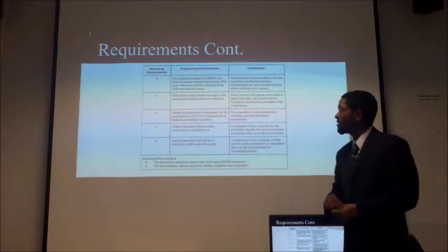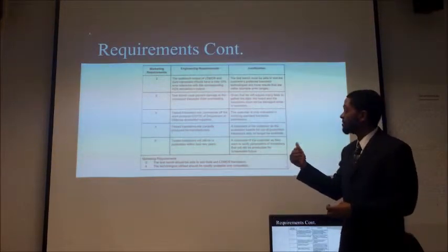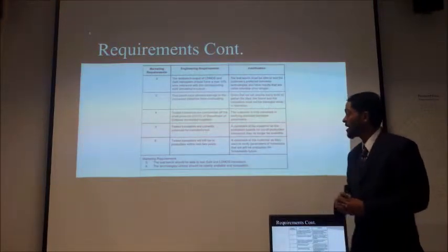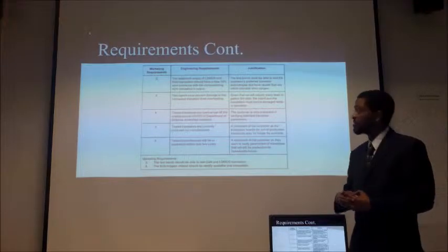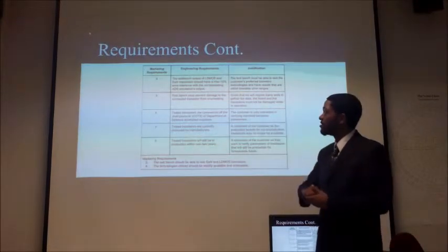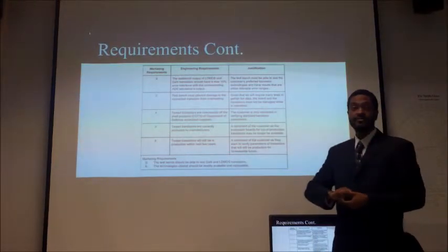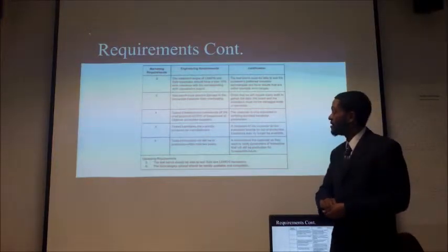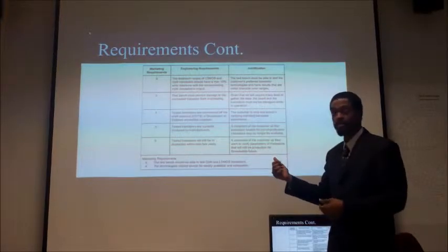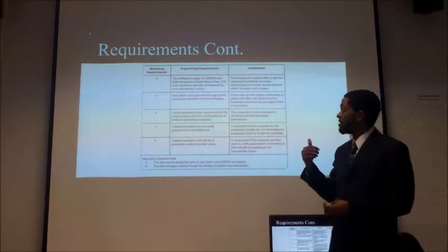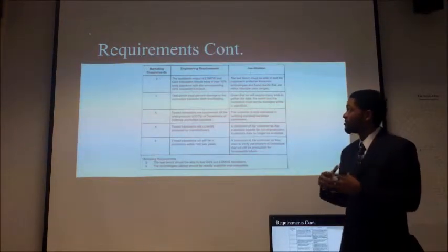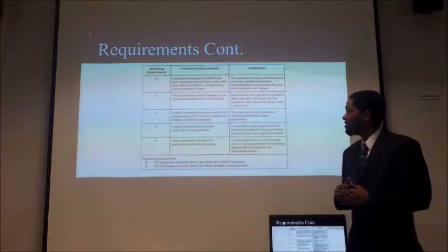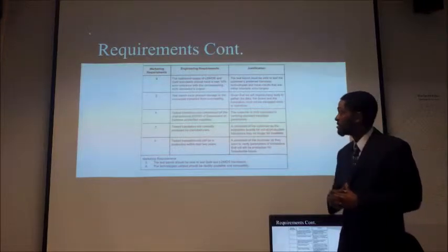Moving on, the next engineering requirements were derived from the marketing requirement that the test bench should be able to test gallium nitride and LD-MOS transistors. The first engineering requirement is one that we modified since our previous project proposal in order to make it more in line with marketing requirement number 3, and it's such that the output of the LD-MOS and gallium nitride transistors should have a max 10% tolerance range within the corresponding ADS simulations output.